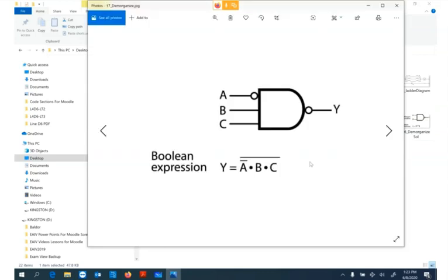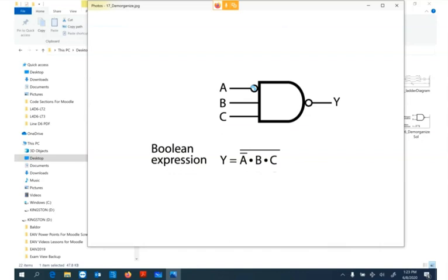So this isn't really a specific instruction per se. It looks like an AND gate or a NAND, but we also have an inverter gate on the input. That's the little bar there. That tells you that's an inverter gate on the input. The ABC is telling us that it's an AND instruction. Now the output negated is represented by the bar over the whole equation.